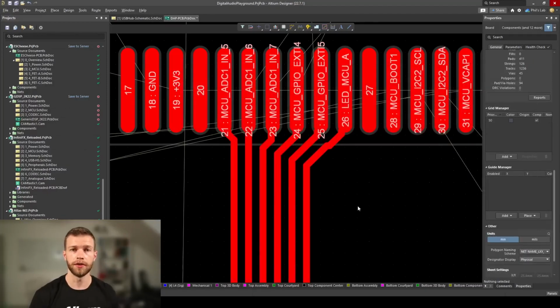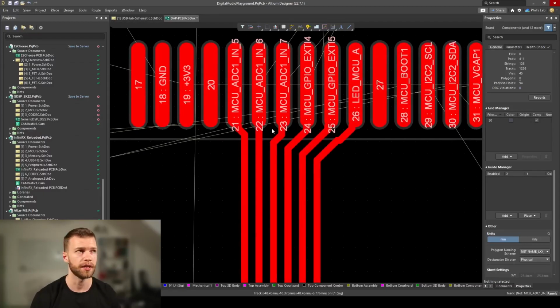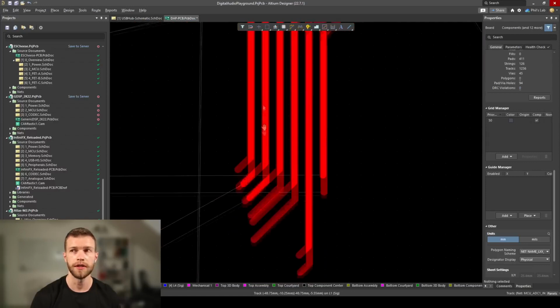Now this is all fine and good, and usually this is the first step a PCB designer should do with the initial board design. But once this has been imported, that doesn't mean you should stick to the minimum clearances and trace widths possible. For example, this design here is a microcontroller with a lot of pins that need to be routed out. This might be ADC channels, digital channels, and so on. What I often see is this kind of pattern. Immediately coming out of the IC, the PCB designer has chosen to simply use the minimum clearance and route all of these traces next to each other.